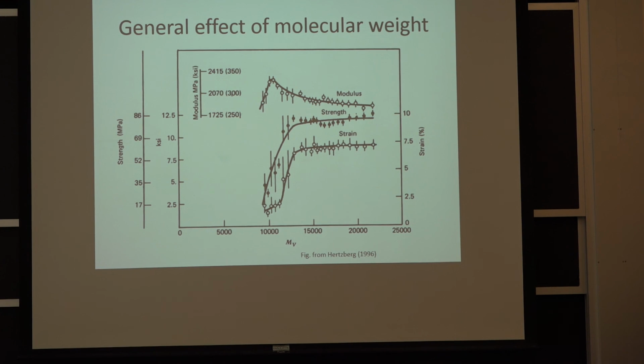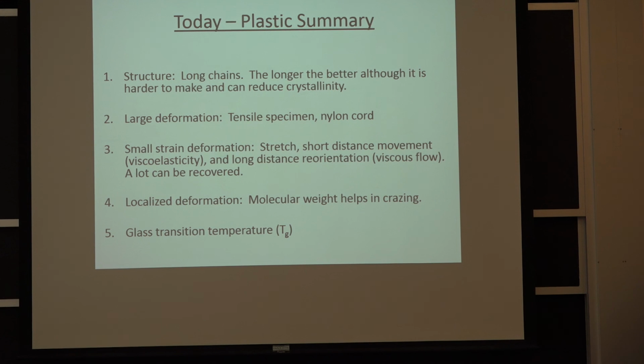The better way, just so you know, to get an idea of molecular weight, it's very hard to know. There's no really easy probe for that, but we look at the melt viscosity. So at a certain temperature, you just slide it through a given opening, depending on flow rate. So the viscosity of the resin at a certain temperature above the melting point is a good indication of molecular weight. So that's used for process control, and it's included in plastic specifications that we'll go over very quickly. I think if you guys have questions, I had some applications. We can go over them at another time. I don't want to take too much time.